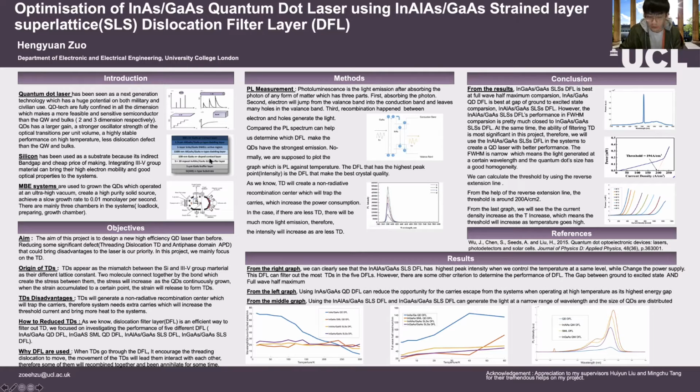So let's move on to the advantages of QD. QD has a larger gain, a stronger oscillator strength, and a highly stable performance, especially at high temperature. And it has fewer dislocation defects than quantum well and box.